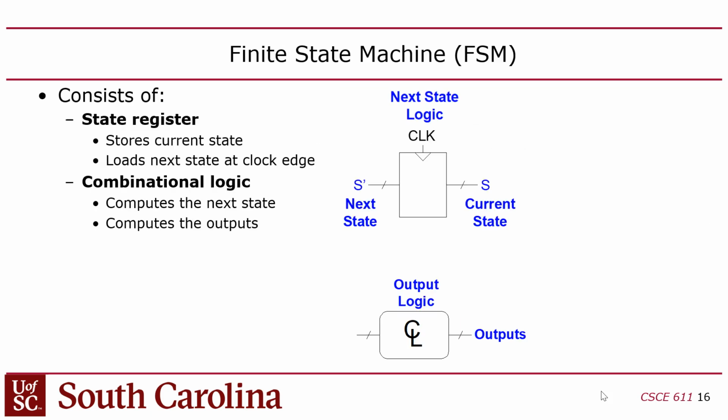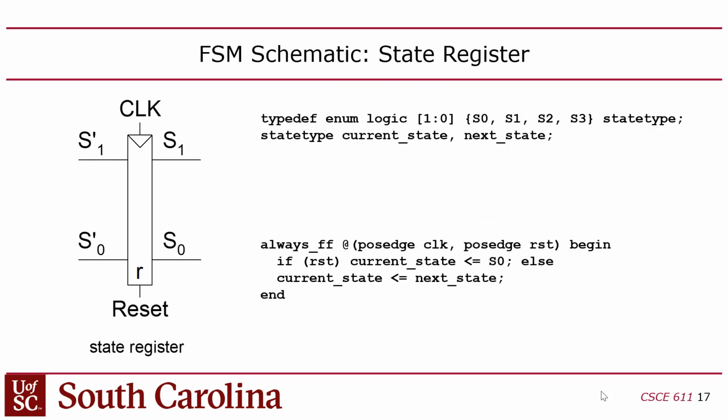What about the Verilog? If you're doing this in Verilog, you still decompose this into the same 3 pieces. But there's a couple of strange things here. In Verilog, you would have to decide your state encodings yourself. You would have to use parameters, which are basically constants. You'd have to decide what binary values you wanted to associate with each state.